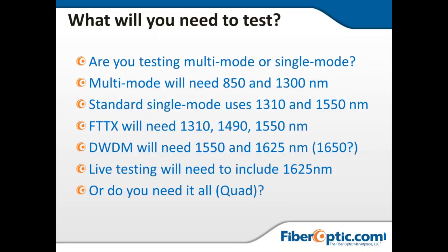The first example of that will be the fiber to the home, FTTX application, where we'll sometimes see this 1490 wavelength come into play. That 1490 is actually the transport signal for the internet as it comes down from the head end. So our Ethernet traffic is going to come down to our NID at that 1490.